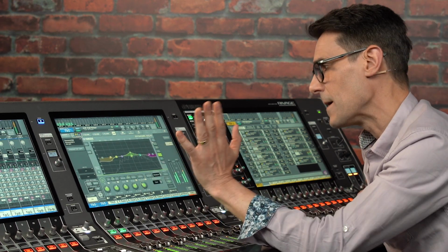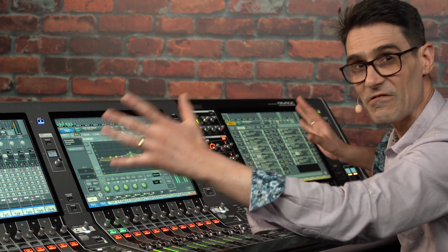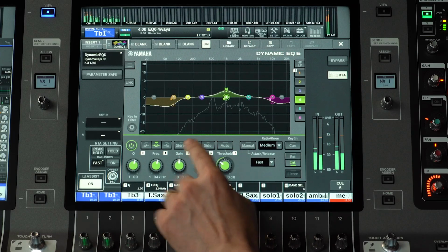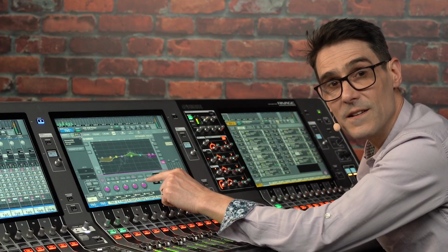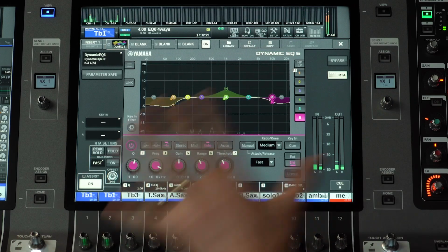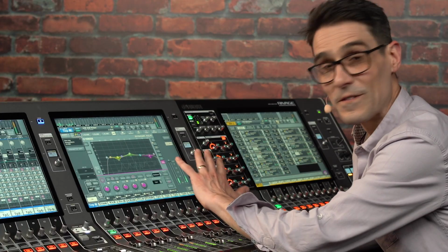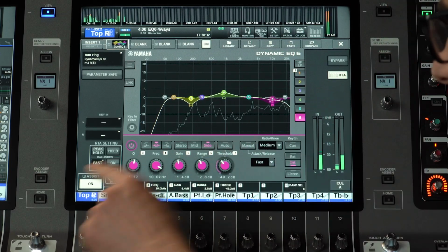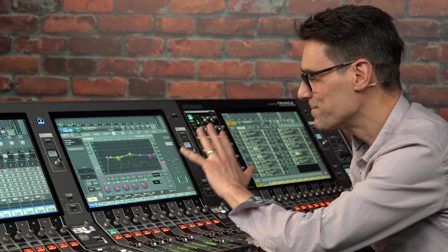In broadcasting, there may be a presenter mic in the center with ambience and crowd sounds either side. So using some bands for mid and others for side will allow the presenter's voice to be enhanced to increase intelligibility.